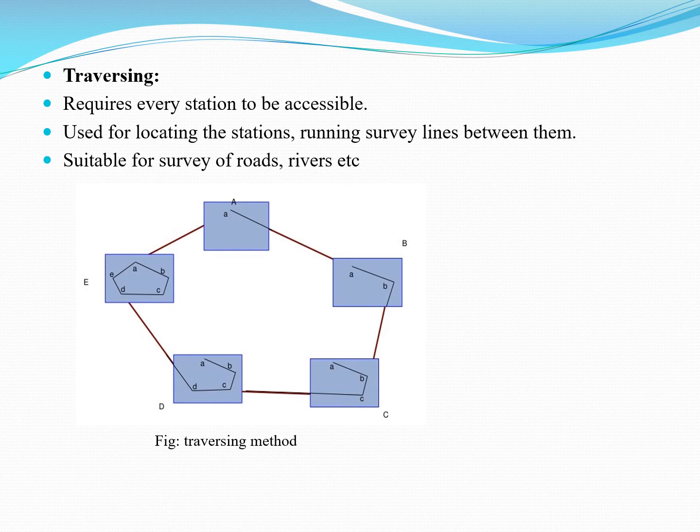Okay, so after that the alidade touching point B, ranging rod at point C is bisected and the ray is drawn. After that the distance BC is measured and plotted by any suitable scale, and again the table is shifted over station D, and the procedure is repeated for all the remaining stations.